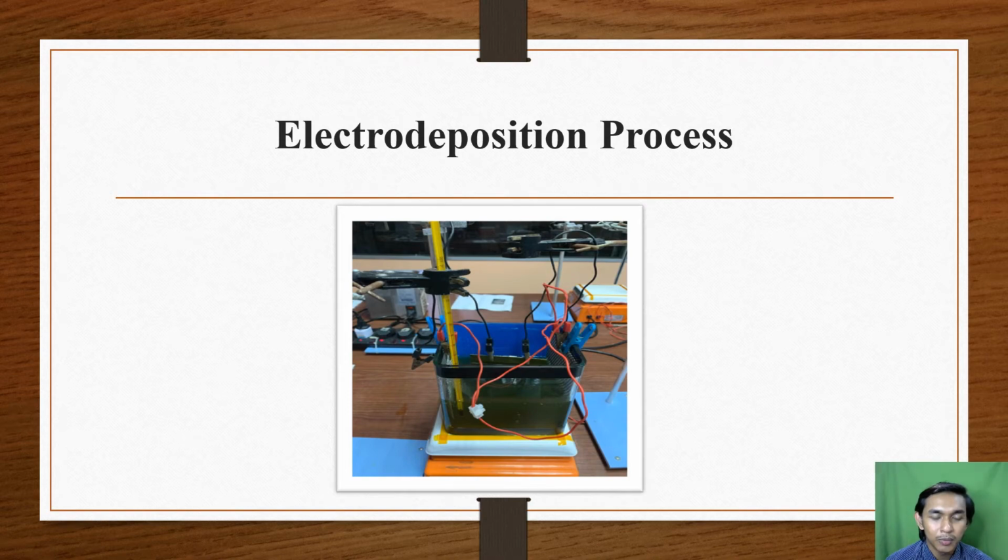The electrodeposition began by turning on the power supply and applying a current of 1 ampere, followed by 2 ampere, 3 ampere, 4 ampere and lastly 5 ampere current density, with a different sample of thin copper plate. Upon completion of the process, the substrate is rinsed using water and dried using tissue at room temperature.